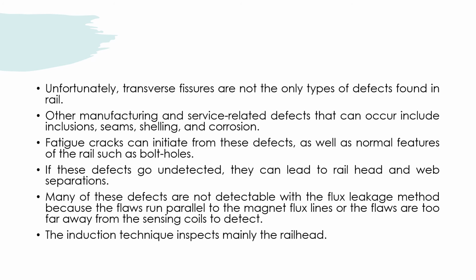Many of these defects are not detectable with the flux leakage method because the flaws run parallel to the magnetic flux lines, or the flaws are too far away from the sensing coils to detect them. The induction techniques inspect mainly the railhead.